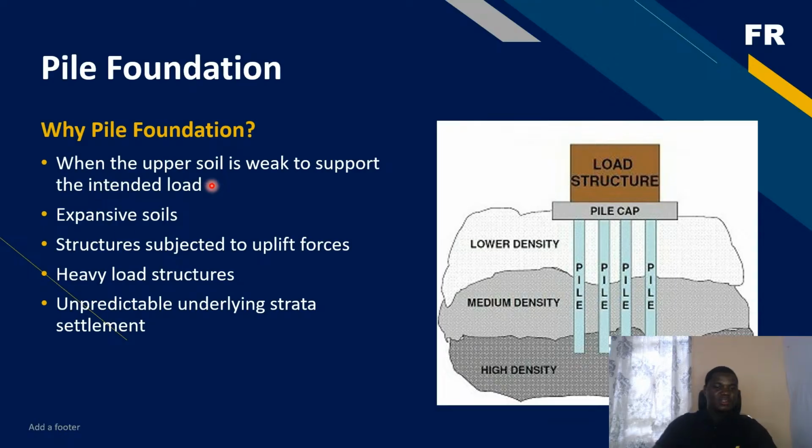And then another situation where pile foundation can be used is for structures subjected to uplift force. This kind of structure includes transmission towers, which are usually on pile foundation, and offshore platforms. These kinds of structures are subjected to what we call uplift force, the force that tries to pull the structure up.